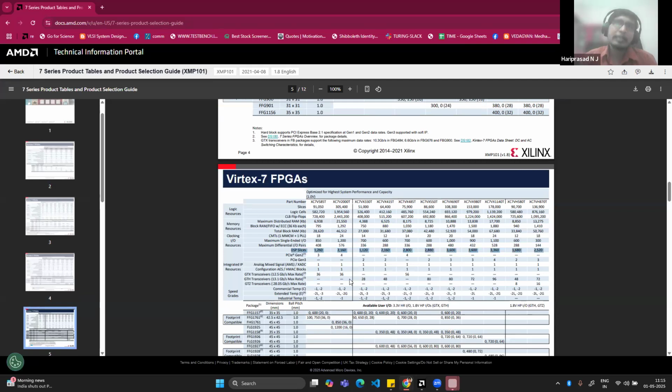Now someone says, okay, 1260 DSP and 80,000 slices is fine, but I need 2000 IOs, so higher IOs. Let's say 600 IOs, 600 single-ended. This 850 supports it, but again this is 850, so 250 extra IOs are there and power may be more. But here I have to go optimal. So you can see here 600 IOs, 2000 DSP slices, and I have 86,000 logic slices. So I can go with this, right?